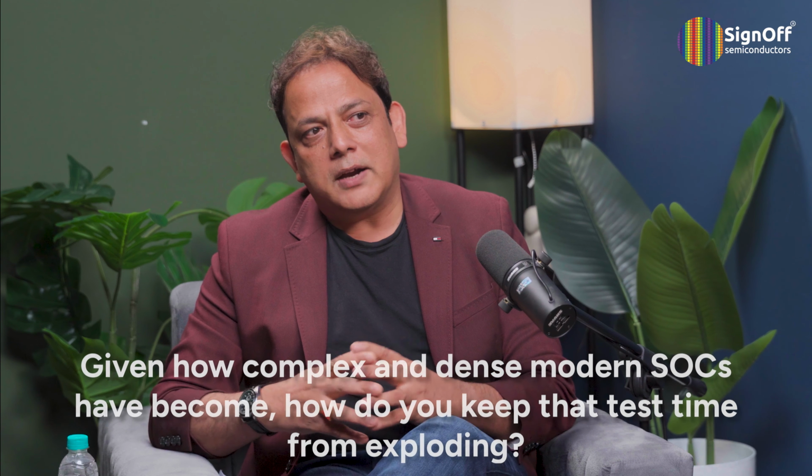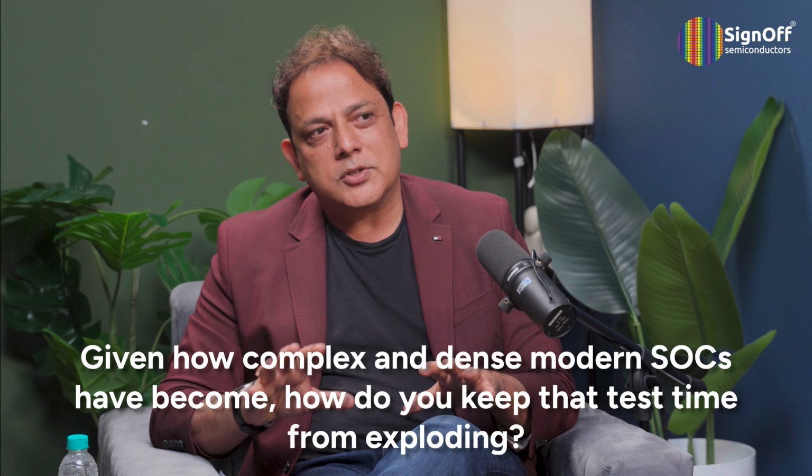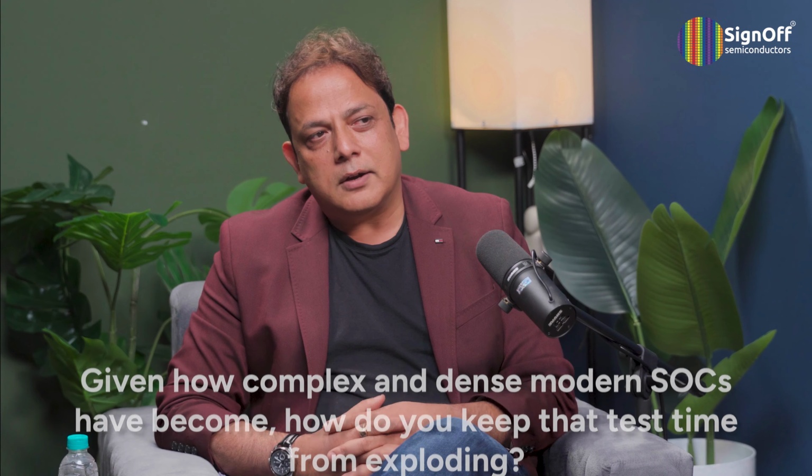So, well, you've addressed the cost element part of it. Now, seeing the complex, dense, and cutting edge chips which are coming on board, the test time factor is exploding. So, how do you control that factor? Because cost has been controlled. The time taken to test these chips is also a critical factor because time to market is very important. So, how do you do that? So that is where exactly we have come up as a DFT engineer. We have come up with a technique called the compression technique.